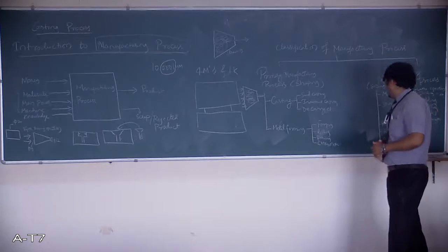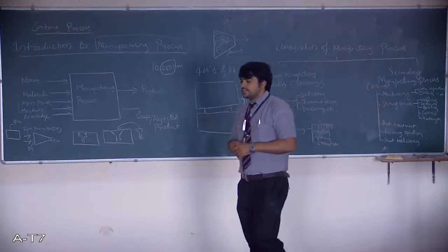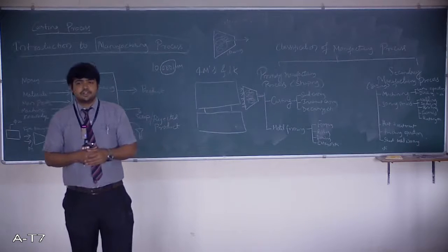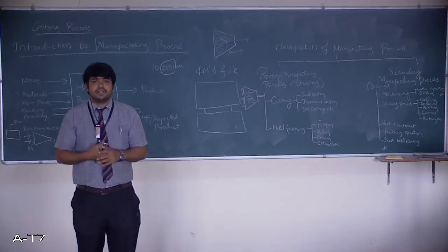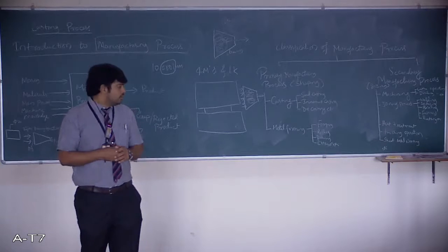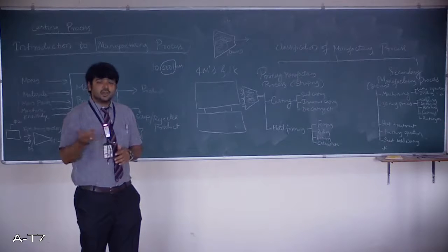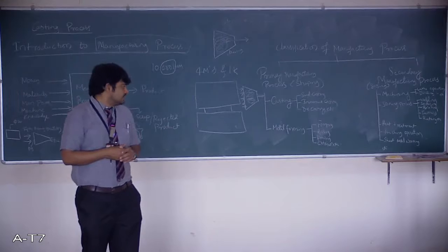Next we have finishing operation. In finishing, what we generally do is make the surface smooth either by painting or polishing. Some projections will be there; those can be deburred. All these things are done in finishing operations. Even galvanizing and coating can be done. So those are considered in this finishing operation.